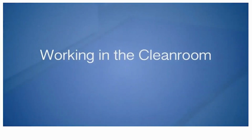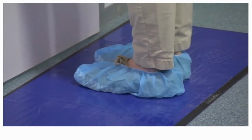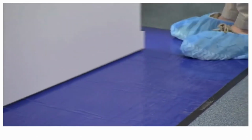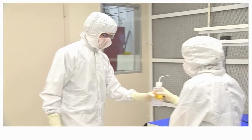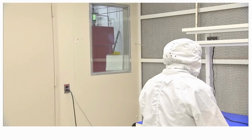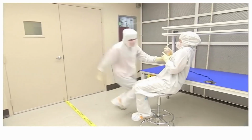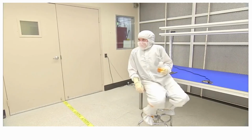Working in the clean room. When entering the clean room, there might be another adhesive sticky mat in front of the door. Be sure to step on it before entering. When in the clean room, practice slow and methodical movements so as to minimize the amount of particles you release in the air by moving. Moving around quickly can introduce nearly 50 times as many particles as moving slowly.